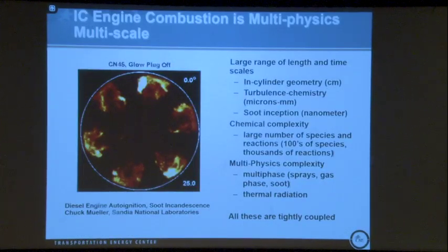And then beyond chemical complexity, we also have to deal with multiphysics. So we have turbulence, gas phase chemistry, but most hydrocarbon fuels start out in a liquid phase, and so you have to atomize and vaporize the fuel and mix it to form the proper mixture, proper ratio of fuel to air, and sometimes diluents like exhaust gases to form the right mixture that you want to combust.